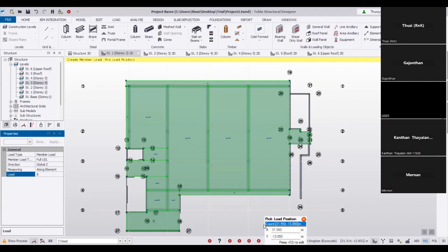Actually, I am doing an approximation because 4 meter is the floor to floor height, from slab to slab, right? But below your wall, you stop at the beam. You can reduce the beam depth and apply it. In your project, you can do your own. You can calculate exactly and apply it. But for easy purposes, I use a simple calculation and apply it.